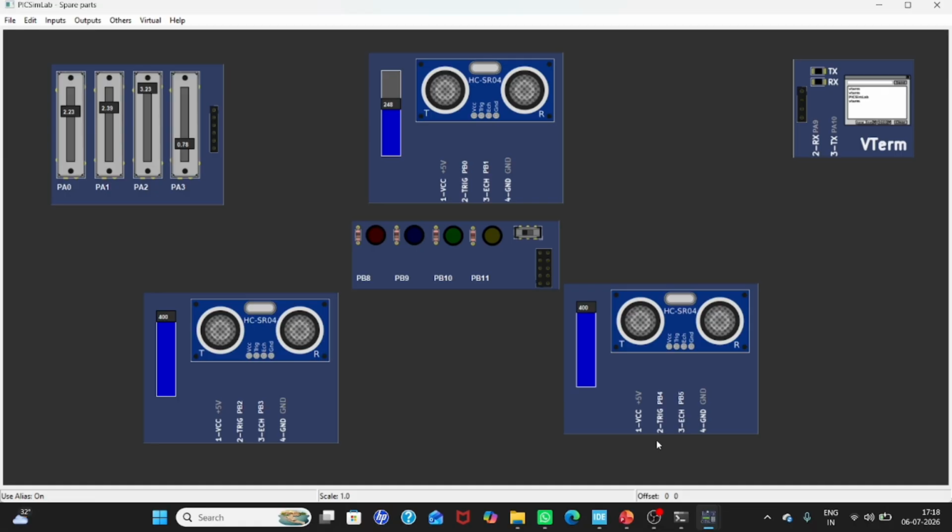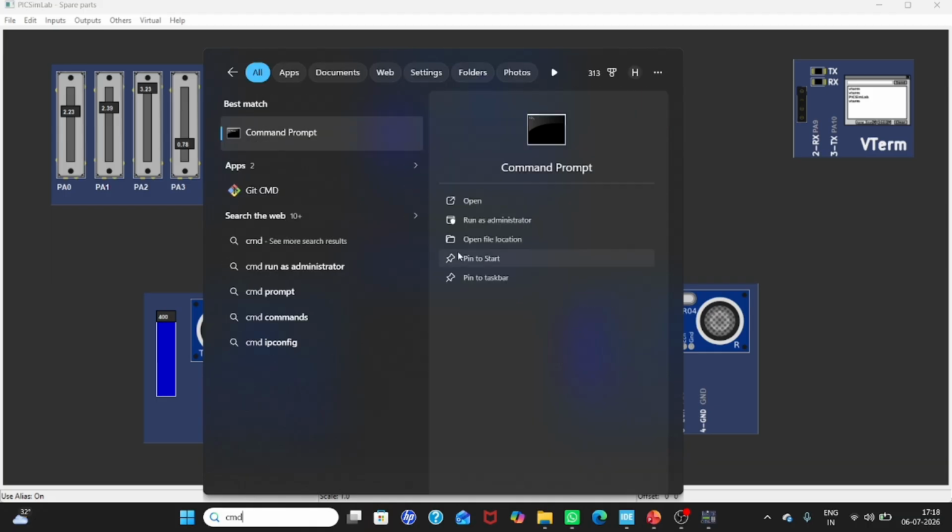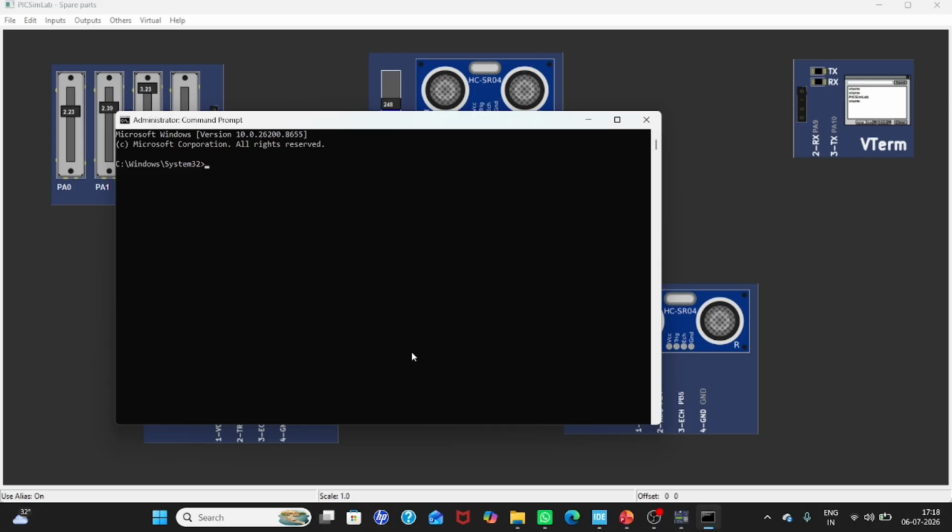The STM32 continuously reads inputs from simulated sensors like accelerator, brake, motor temperature, and ultrasonic sensors, and it processes the data using EV control and ADAS algorithms, detects faults or unsafe conditions, and sends real-time telemetry using UART.